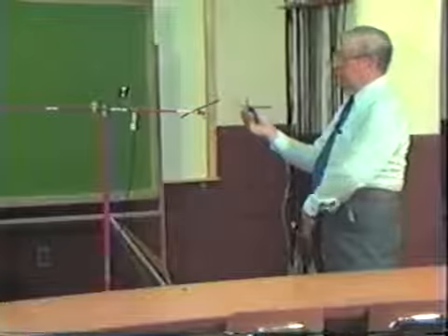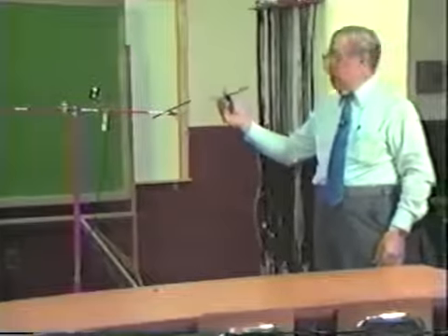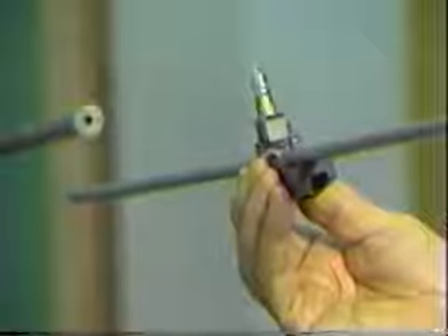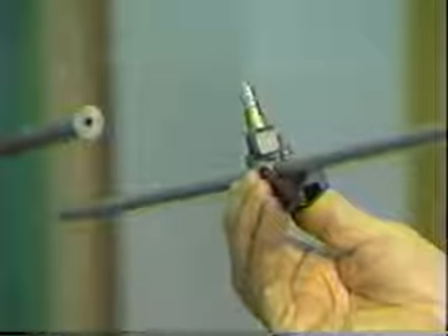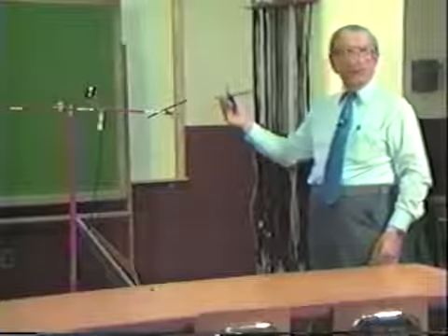And the transmitter is on. You can see the little incandescent lamp lit. And I want you to notice that there's absolutely no pickup. Well, there is some pickup, not enough to light the light. But I want you to see the front to back ratio of this beam antenna.